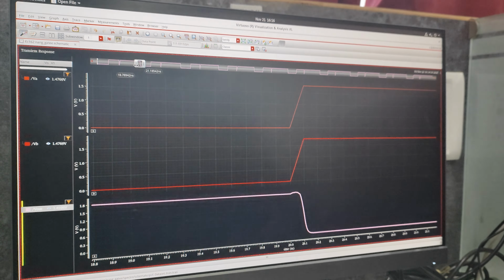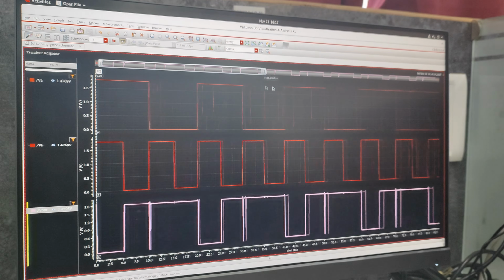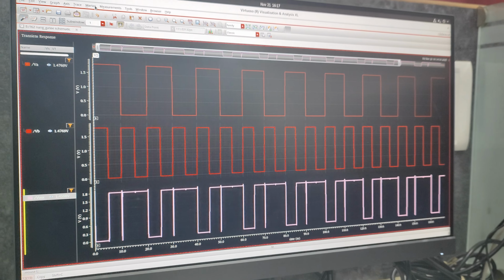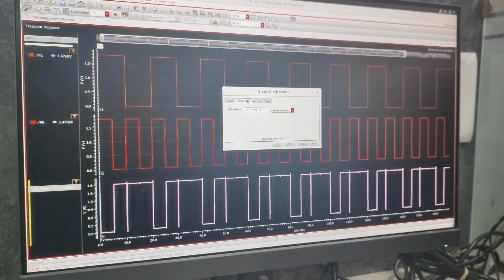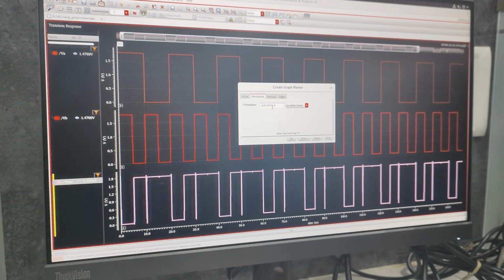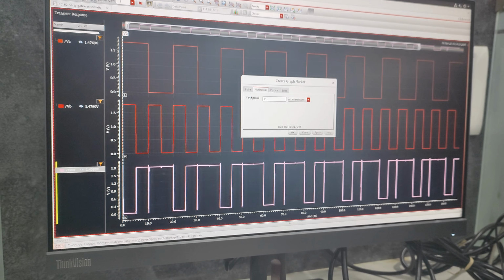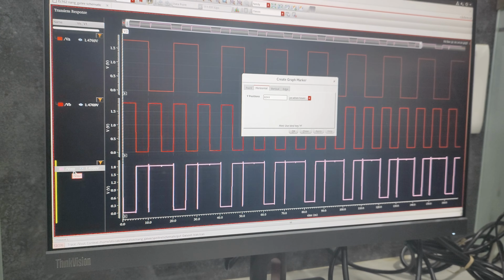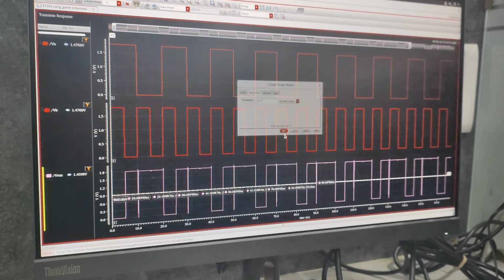Okay, after this, you may be asked to do one more thing, TDR or TDL. So for that, what you have to do is, in this, again come to marker, create marker, come to horizontal. In this, voltage is there, no? What is the maximum voltage we kept? 1.8 volt. Keep it as 0.9, half of 1.8 value. Okay, for one thing, V out. Click on apply, then click on OK.